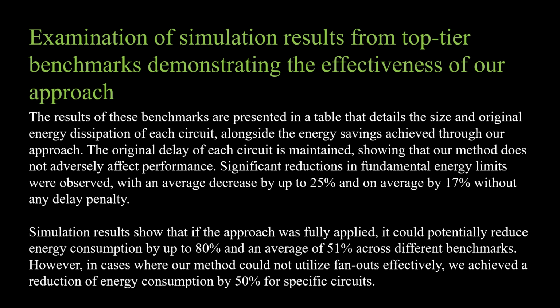Significant reductions in fundamental energy limits were observed, with a decrease of up to 25% and on average 17% without any delay penalty. So here simulation results show that if this approach was fully applied, it could potentially reduce energy consumption by up to 80% and an average of 51% across different benchmarks. However, in this case, where our method could not utilize fanouts effectively, we achieved a reduction of energy consumption by 50% for specific circuits.